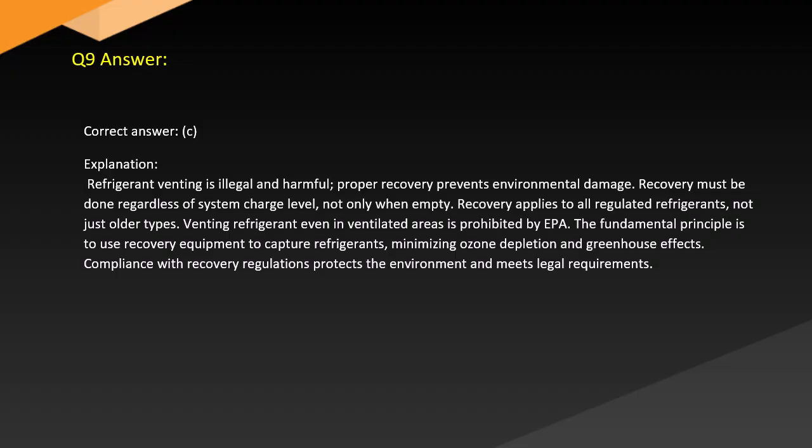Answer. Correct answer: C. Explanation. Refrigerant venting is illegal and harmful. Proper recovery prevents environmental damage. Recovery must be done regardless of system charge level, not only when empty. Recovery applies to all regulated refrigerants, not just older types.